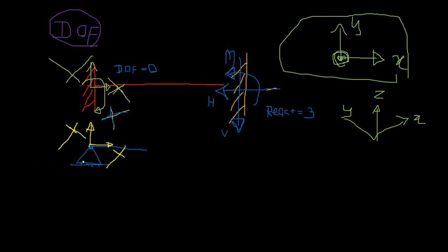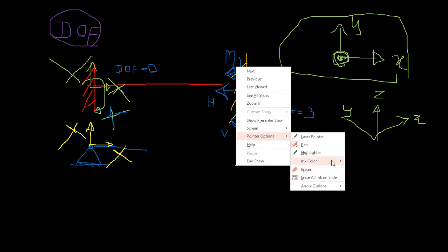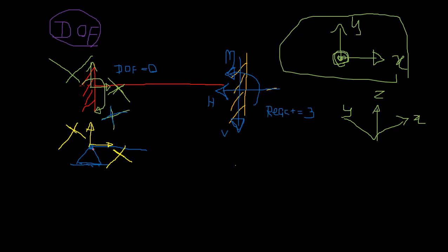So this is a cross mark, okay? It is not allowed. But think about the rotation. It is not restricted, right? So if this beam is loaded, it can rotate like this, right? But here, if it is even loaded, this part, the closer to the support, is not rotated, so it will remain as it is, but towards the middle of the beam it will deform, right?